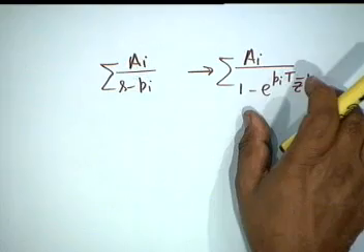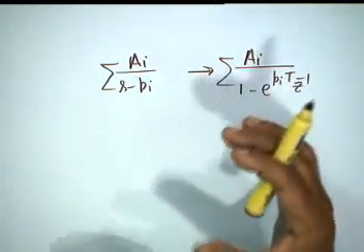These are two ways of looking at it: one is the aliasing point of view, and the other is that aliasing occurs because we have no control over the zeros. On the other hand, in bilinear transformation, we transform poles as well as zeros. We transform the total function. This is one of the weaknesses of the impulse invariant transformation.